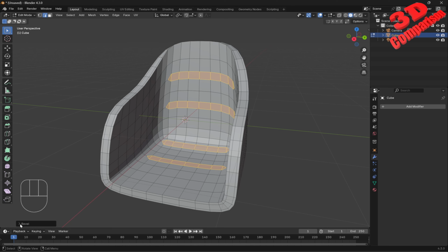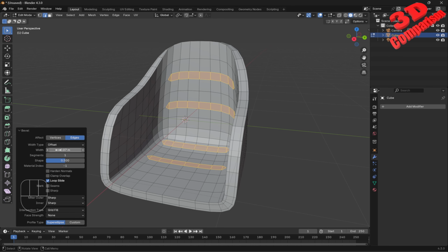And now I will go within that last operation, which will be on the bottom. So this will be the bevel, and we can change various parameters. So for example, the number of segments, in this case I will go with 3. We can also change over here the profile. So we're going to see patch or sharp or arc over here. We can also change this on the fly, so for the numeric value, but I'm just going to leave this to 0.07 in this case. We can also change the shape over here. As we can see, this will be from 0 to 1.